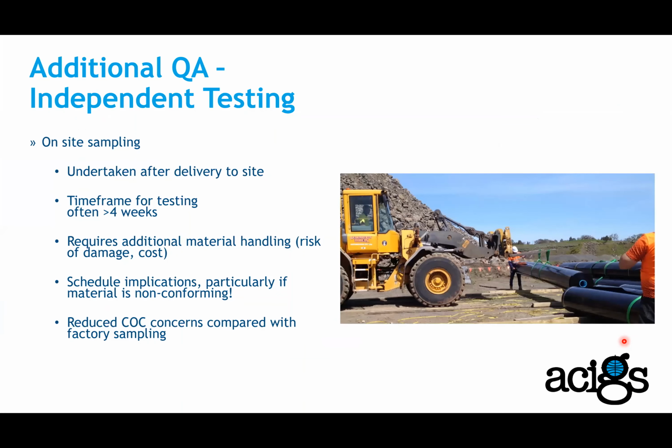The other approach is sampling on site. So basically, this is undertaken after delivery to site. So material comes on site, and the time frame for testing is often more than 4 weeks. So we need to consider that. The material is on site, but we can't use it because it's not approved for use until all the test results are back. And that's obviously impacting the schedule for the construction. It requires additional material handling, and there is a risk of damage and cost associated with that.